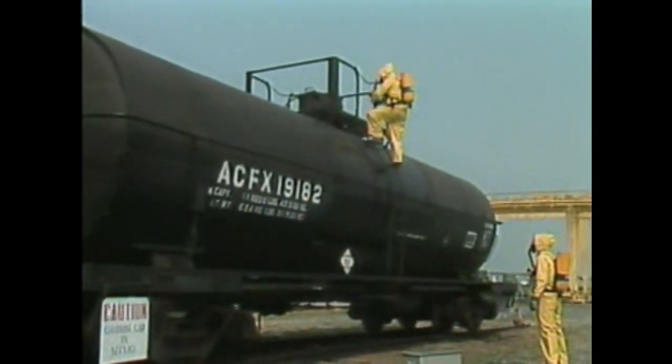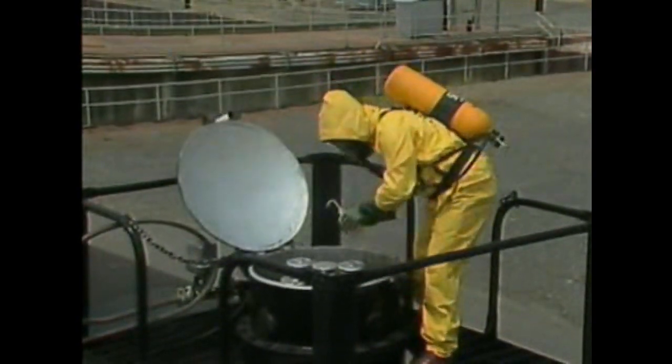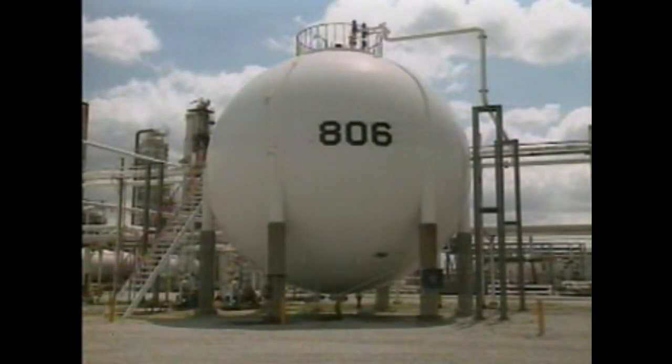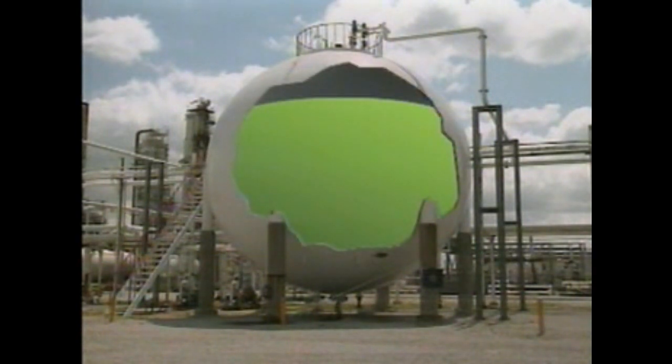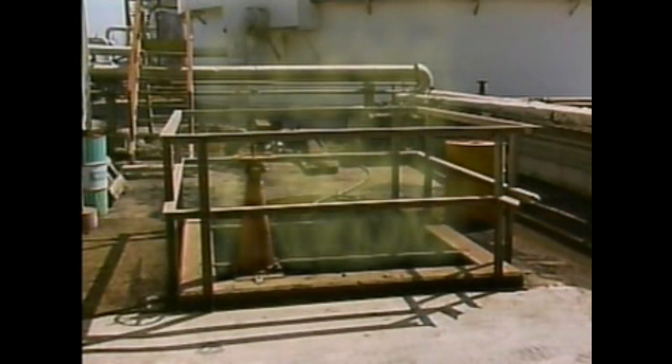If the emergency is an uncontrolled release of a substance, the escape procedure will depend on the density of the vapor that has been released, among other things. Vapor density indicates whether a gas is lighter than air or heavier than air. Materials that have a high vapor density tend to flow down into low-lying areas. Liquid propane gas is an example of a material with a high vapor density, so it will fall in the atmosphere. And materials that have low vapor densities tend to flow upward into the atmosphere from their point of release. Methane is an example of a gas that has a low vapor density, and it will rise in the atmosphere.